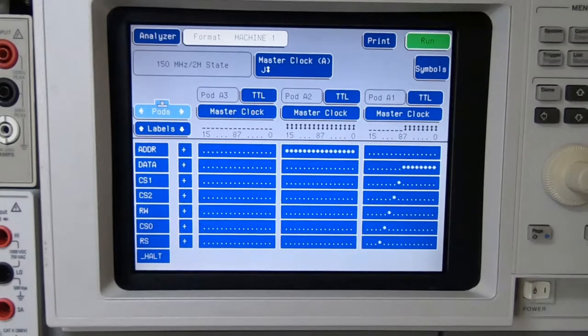So to start, what you need to do is look at the spec sheet for the particular processor that you're going to use, or that is in the machine that you're working on. And so that's what I did here. For this particular processor, I wanted to find the program entry point. In other words, I wanted to find the reset vector for the processor. That's the address the processor jumps to whenever it is reset.